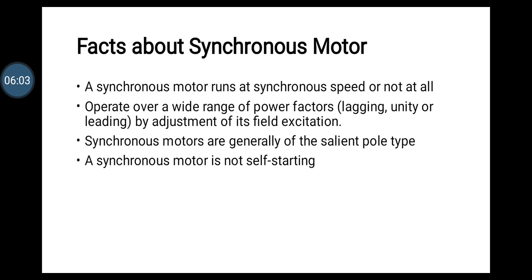Second thing, the machine operates over a wide range of power factors, lagging, unity, or leading power factor, by adjustment of its field excitation. The outstanding characteristic, that means the best characteristic of the synchronous motor, is that it can operate at a wide range of power factors.